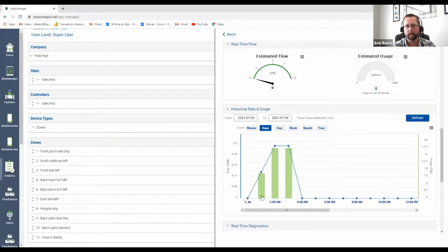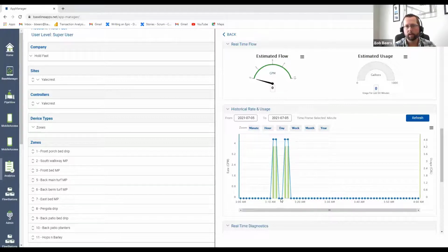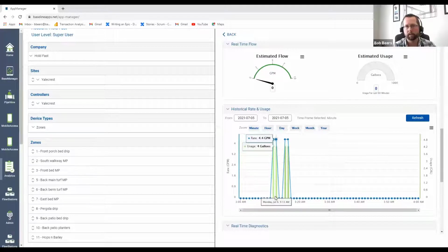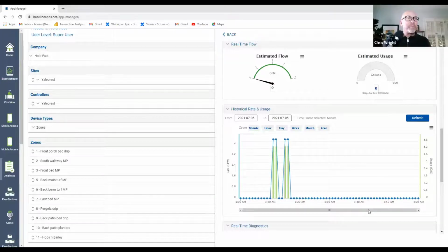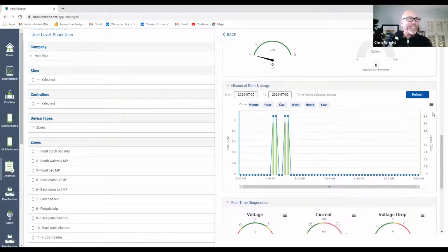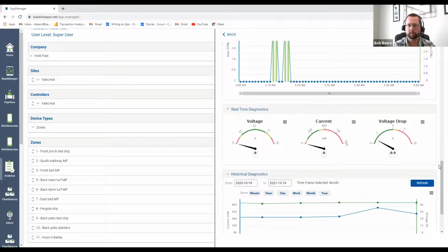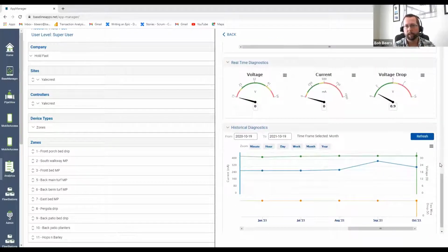And then looks like we could see all the way down to the minute level. Is that a soak and cycle? Yep. On, running, off, and then cycle back on until it hit its runtime requirement. Best management practices. Cycle soak. And then you could call that out. You could export it. And this is exactly what we'd want to see for best management practices. It's implemented, and you have proof aside from your programming model, but here's actual captured events where it's being implemented.